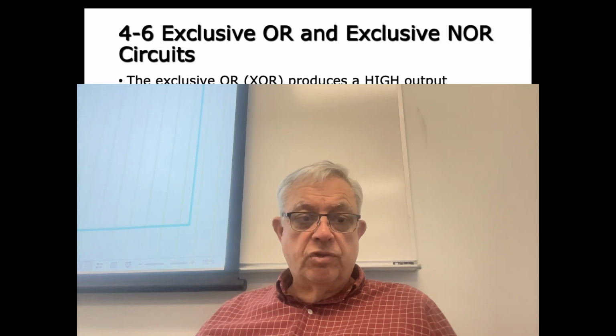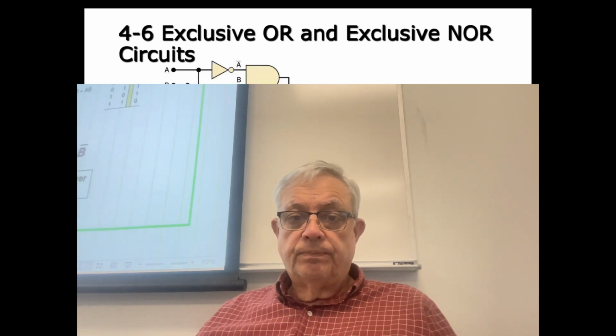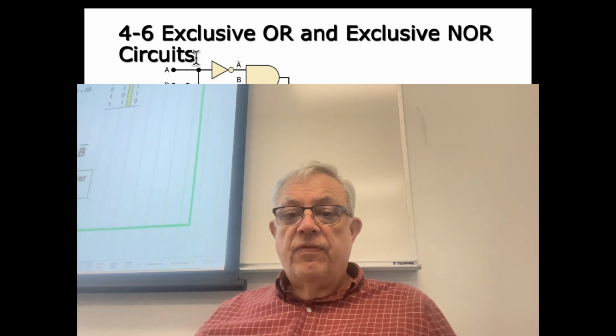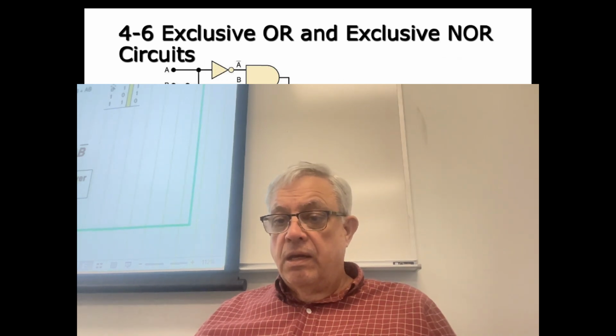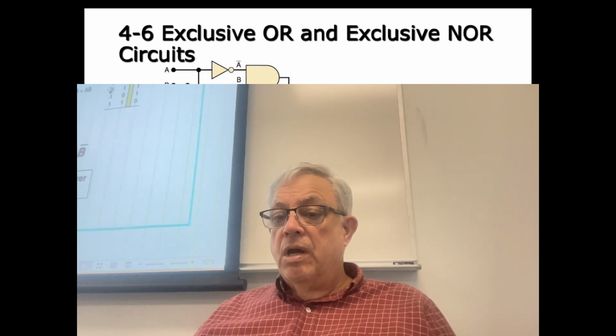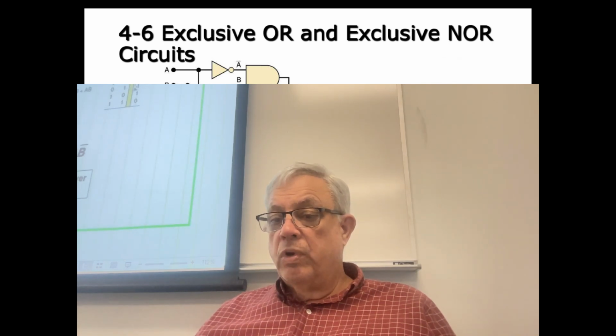Exclusive OR, exclusive NOR. This was a fun one. Exclusive OR. If A and B are both 0, then the output is 0. If A and B are both 1, the output is 0. If A is 0, B is 1, I get a 1.